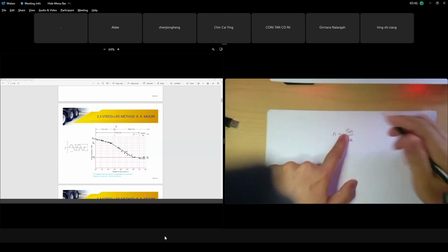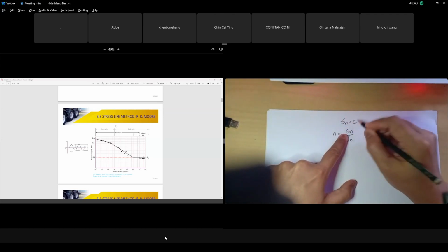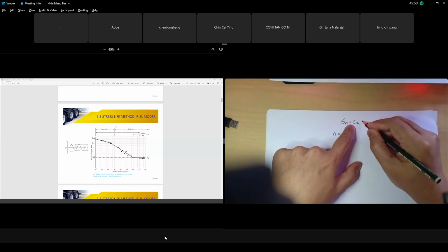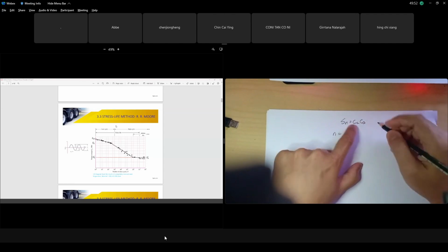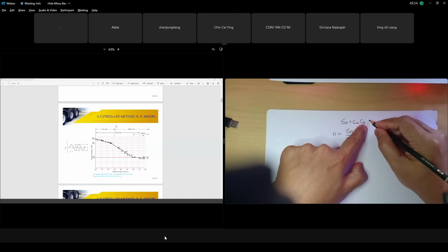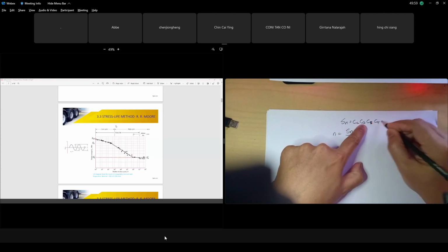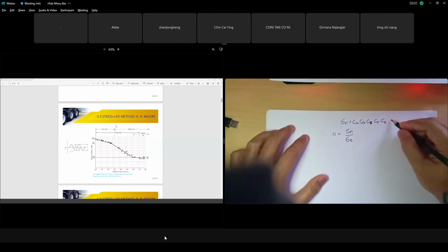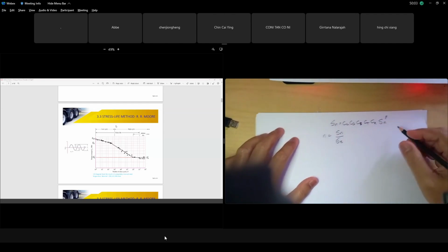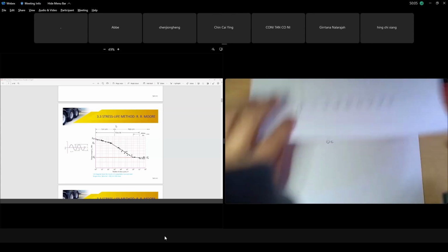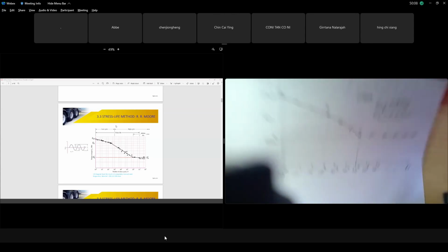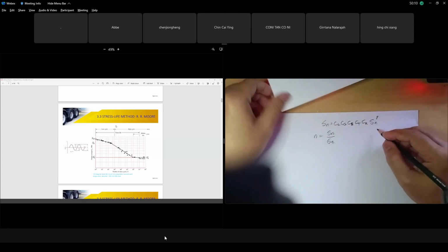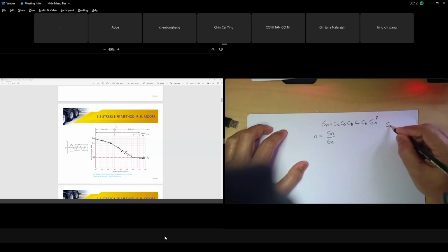What is your SN just now? I will explain the modification factors later; it is pretty easy and straightforward. You can get it from your textbooks. SN equals load factor, gradient factor, surface factor, temperature factor, and reliability factor times your SN prime. We know that SN prime, the one I explained to you, from the standard specimen test, is 0.5 of your SUT.